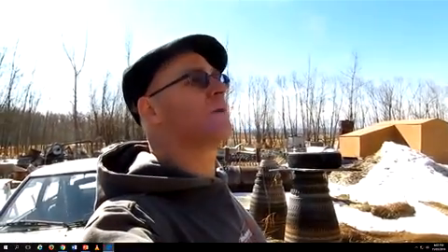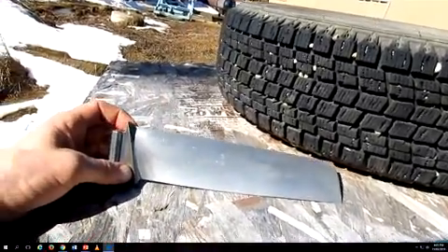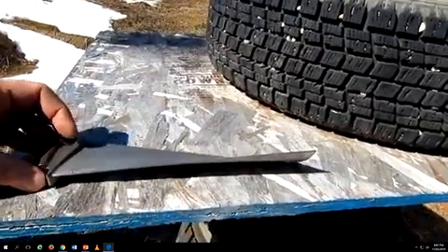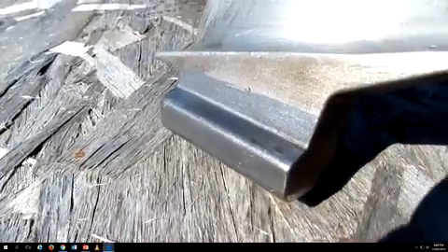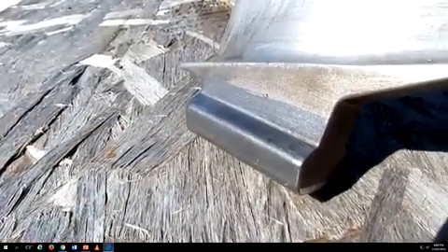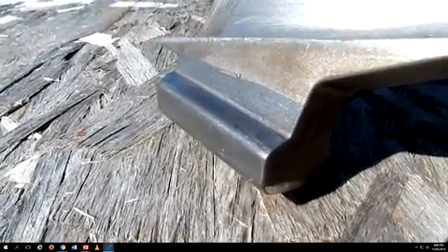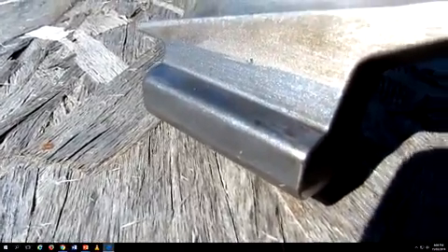Okay, we're out here in the graveyard of turbine engines with a turbine-powered helicopter in the distance to look at how a compressor blade wears out. There's two examples on this one right here. This is a stage 1 blade from an LM1500. And let's see if we can get in there real close. Okay, we're moving in here to the blade root. This is the surface that bears the centrifugal load of the spinning compressor rotor. And I hope you can see there's some wear. This blade, on inspection from removal of an engine, was decided there's too much wear there, so we junked it.